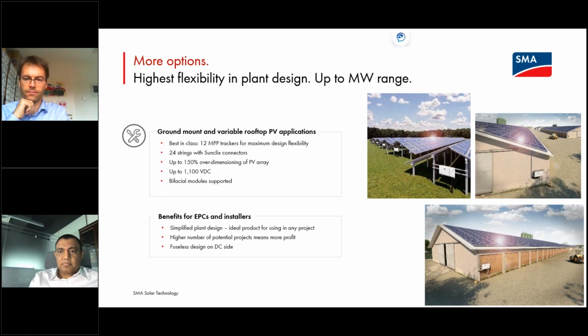So you can go to Sunny Design, bring in a Google Earth picture of your project, of your company hall, and then you can simply integrate different angles and directions of your rooftop PV arrays, and simply design the system as if you would do it with small PV inverters such as Sunny Boys from us. So the design itself, also with our tool Sunny Design, is really simple.